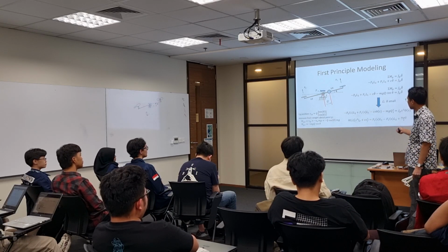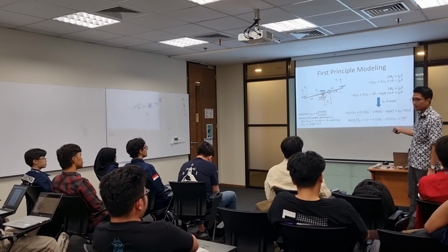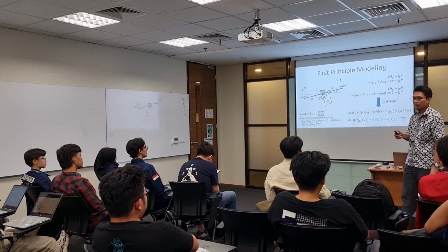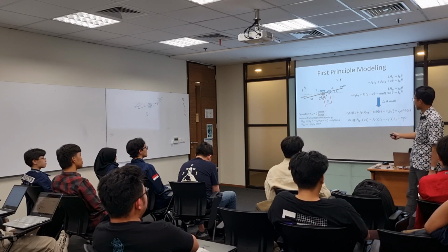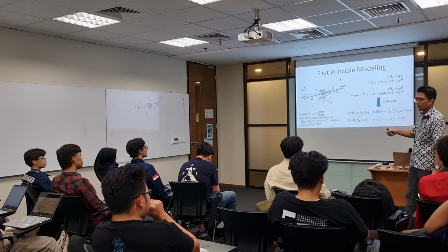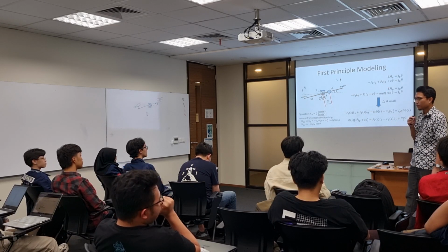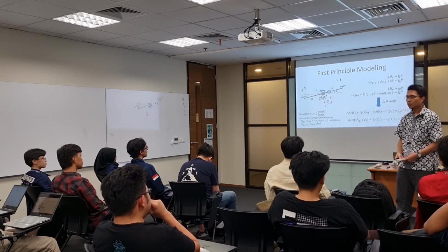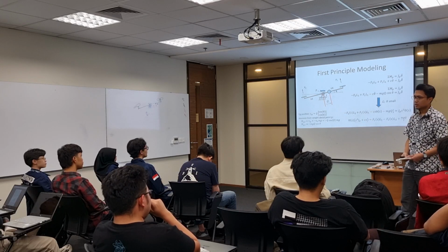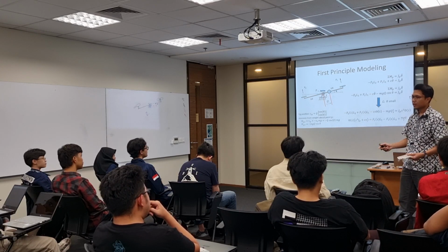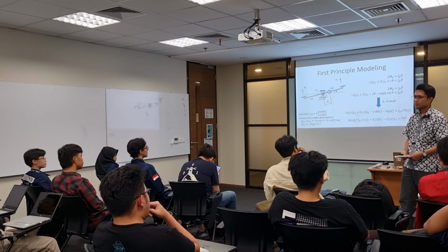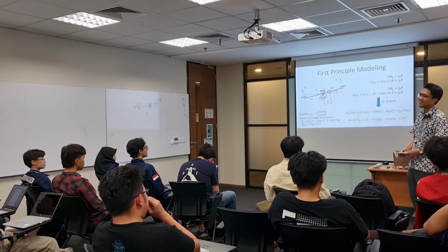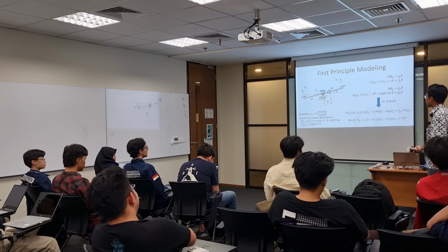Which is shown here. The term cosine theta here is non-linear already. I haven't converted into Laplace transform yet. This one is still in differential equation. We haven't gone into the thrust relationship yet, and the model is already non-linear. Laplace transform cannot handle a non-linear model, to the extent you learned. It cannot handle the non-linear model.